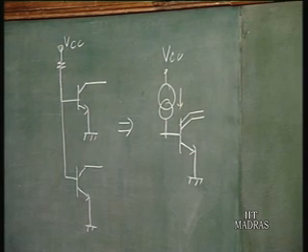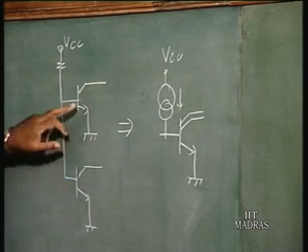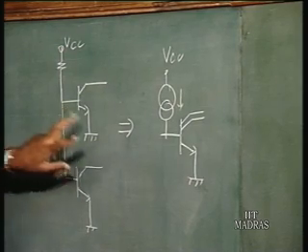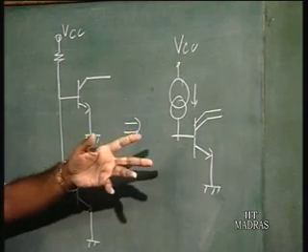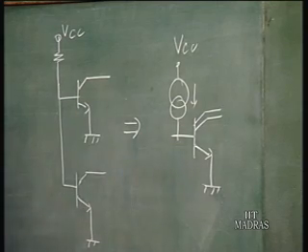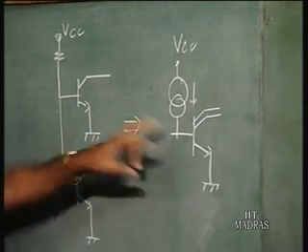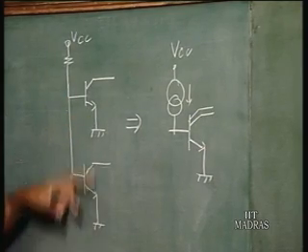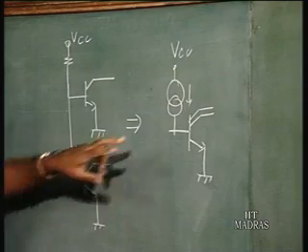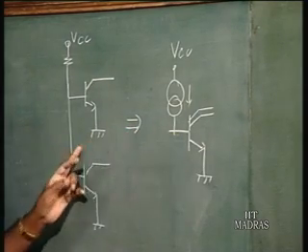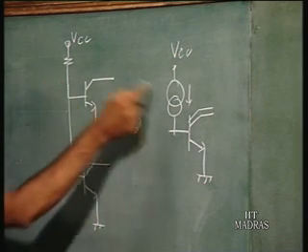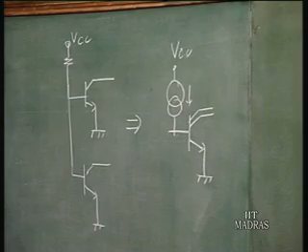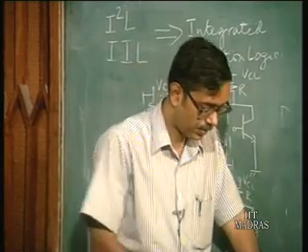That is basically what we are looking at: here the two base emitter junctions. If you have a transistor with a common base emitter junction, then of course you do not have the problem of current hogging, because there is the same base emitter junction. Because these base emitters are in parallel, these emitters are grounded and the base points are shorted, you can have a common base emitter junction and multiple collectors. A transistor with common base emitter junction and separate collectors, and instead of this resistance you have this current source. So, you can think of it this way.